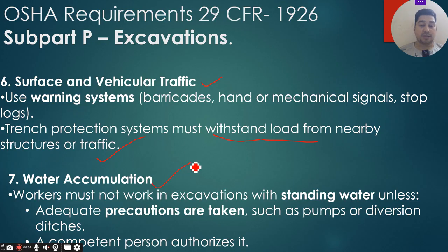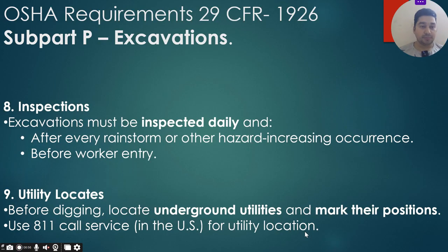Then we have another hazard, water accumulation. OSHA says that workers must not work in an excavation with standing water, unless adequate precautions are taken, such as pumps, diversions, ditches, or a competent person authorizes it. Only if the competent person authorizes it should the workers start to work. So this is the requirement.